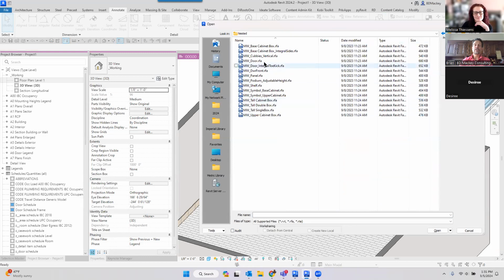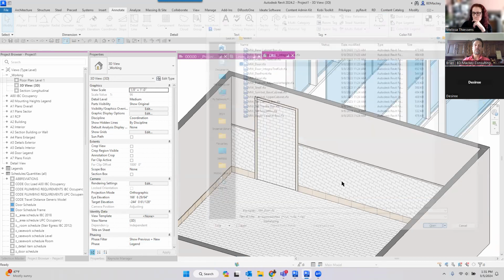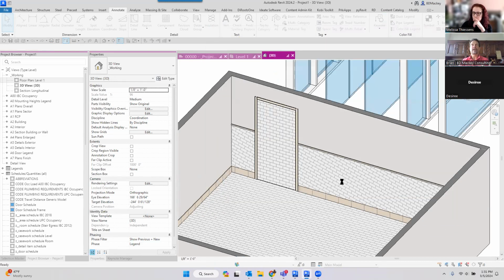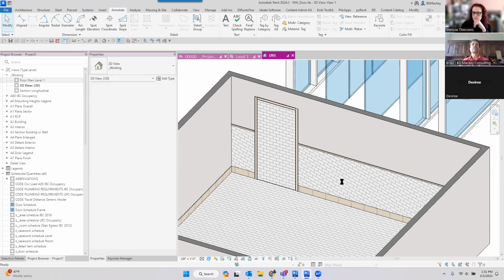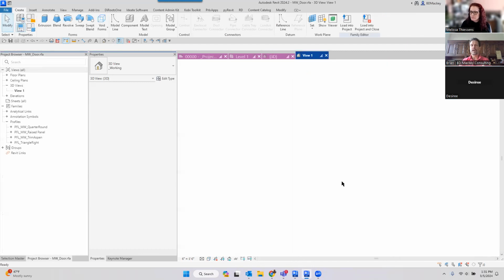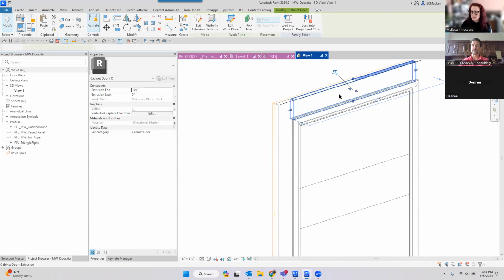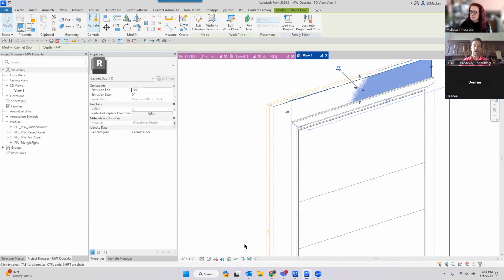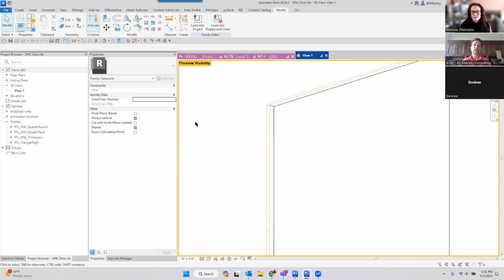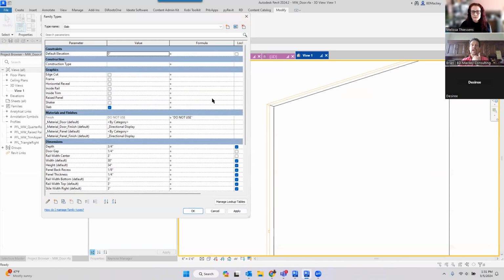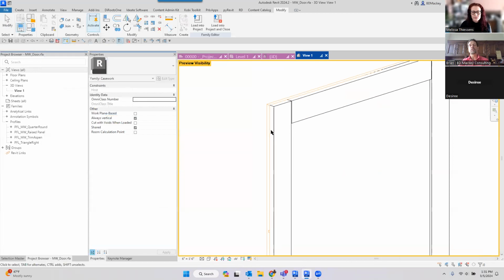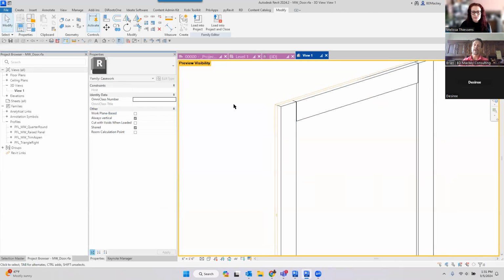What was driving me crazy is in my millwork family for the doors. I modeled my styles independent of my rails. I do the same thing for a lot of my millwork families, because if I'm doing a style and rail type cabinet door, those are going to be different grain directions. This one, I want the grain direction going that way. This one, I want the grain direction going that way, etc. In the family environment, you can go through and rotate and align those hatch patterns.